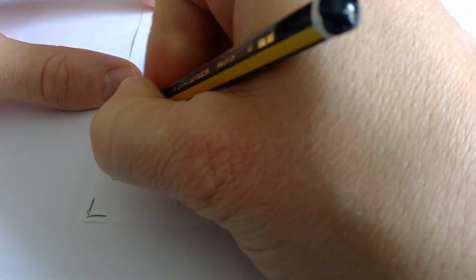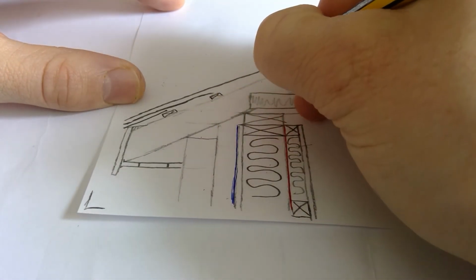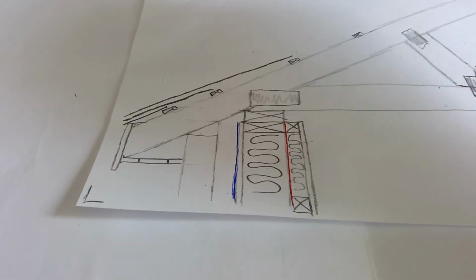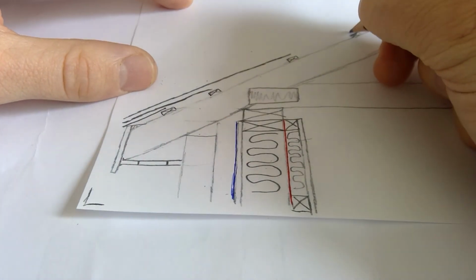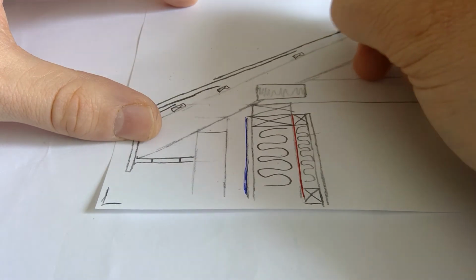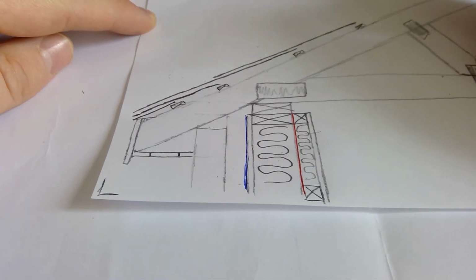And then your last one should come, this takes practice, over there. Now again, that's quite untidy there. It should be neater, you'll see in the solution. And then I do another one, a full slate from the center of this all the way down. Now if you have to go a little bit above 700mm with your slate, that's fine to make it work. That's too much of a gap there.